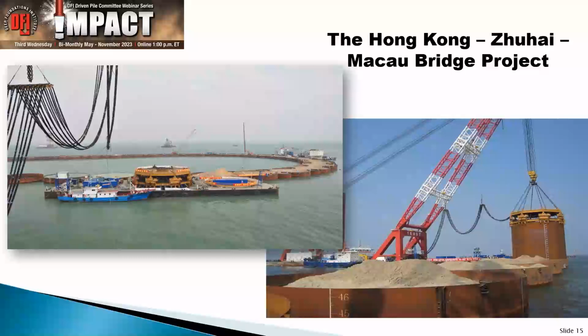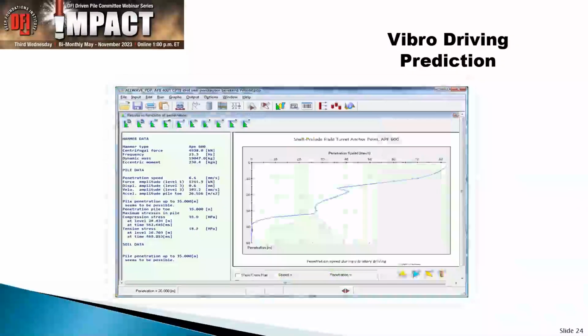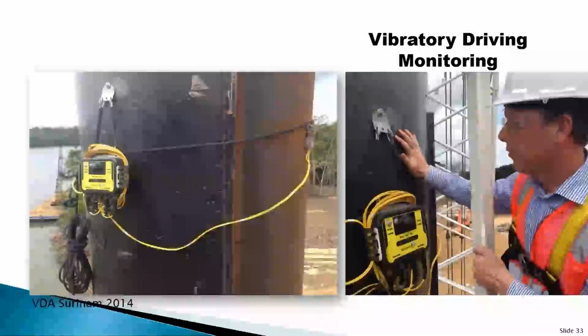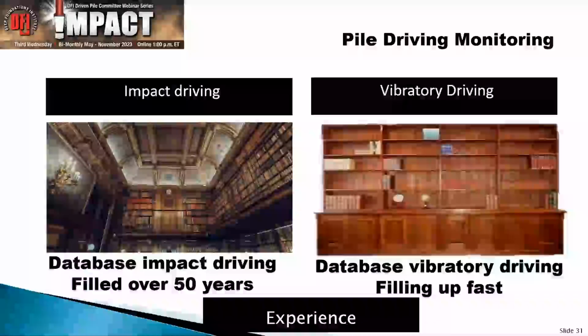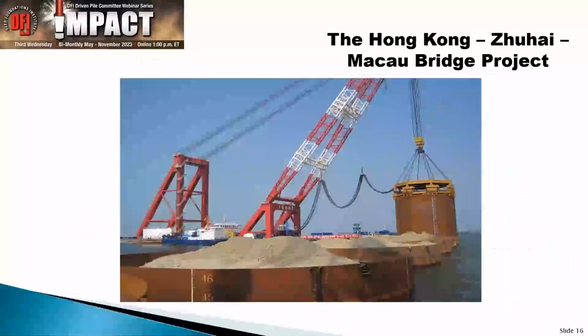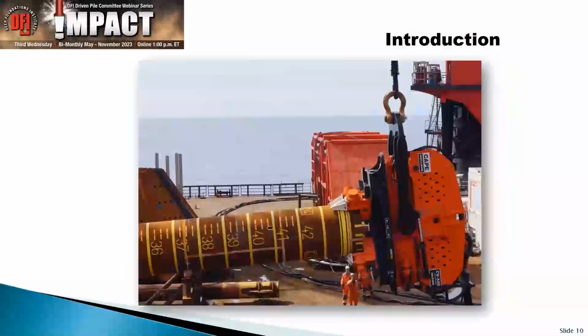If, on the other hand, we have a situation like the project I showed you in Germany, where the hammers sit side by side on a stiff plate, then it's really no problem. If one goes out, you lose some capacity.